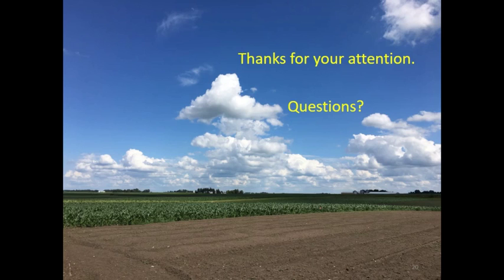Dr. Hammack: Do you have a physical explanation or conceptual model for how the bulk density increased? Why did the bulk density increase over time? How would you explain it? Okay. So the field was tilled, and then with time the soil will compact, and after the rainfall, it also will help to compact the soil. So that's why bulk density increased in the field.